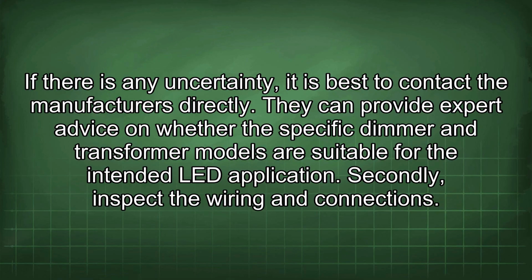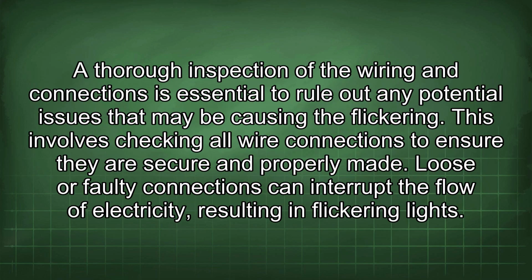Secondly, inspect the wiring and connections. A thorough inspection of the wiring and connections is essential to rule out any potential issues that may be causing the flickering. This involves checking all wire connections to ensure they are secure and properly made. Loose or faulty connections can interrupt the flow of electricity, resulting in flickering lights.